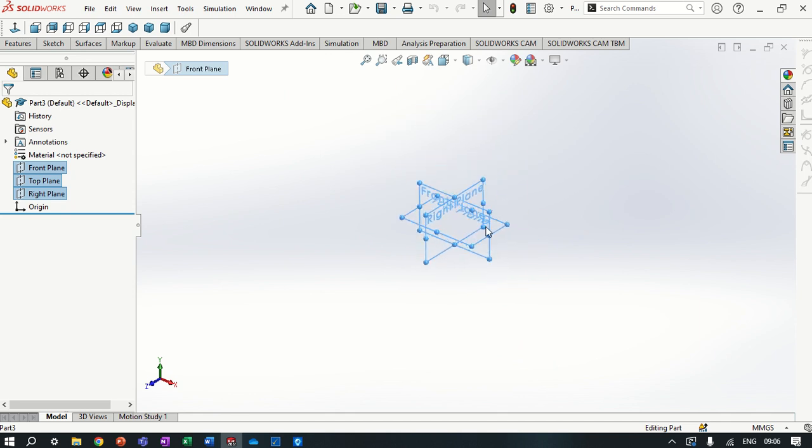I want you to get a bit of practice with this. The zoom is hard to control. Now the way the zoom works is, if I zoom in and out, see the way I'm rolling the scroll wheel there in and out. Look, it's gone off the page. Okay. If you ever get lost, if you can't see your model and it's gone off the page, double click the wheel as a button. So remember that wheel we used a second ago? Double click it as a button.